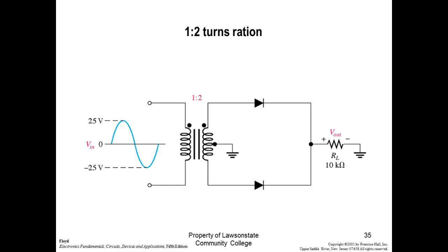That's exactly right, RMS. Go here, Larry. So the first thing we would do, if we know our primary voltage: if it's a step down transformer, then we divide it by the ratio. If it's a step up transformer, then we multiply it by the ratio.